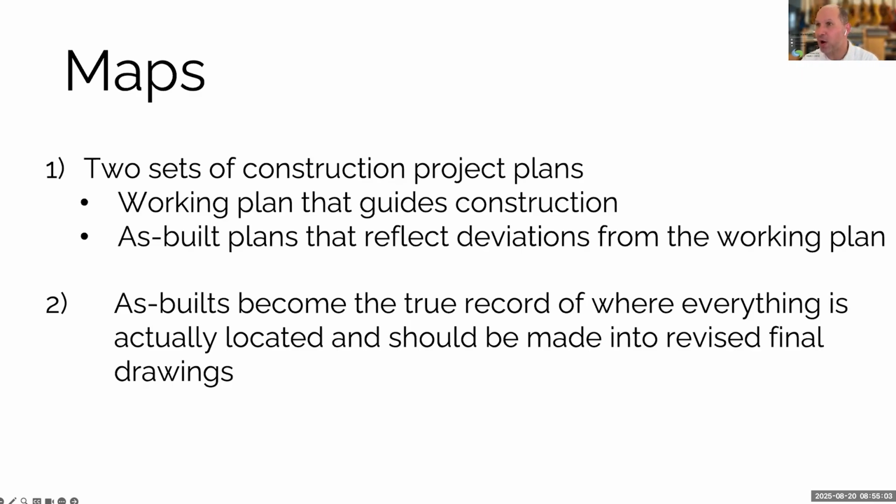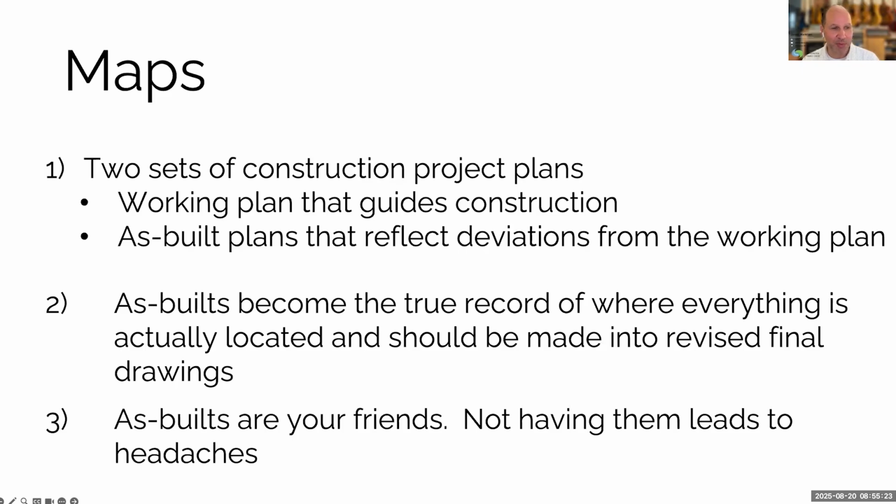It should say final drawings or something like that on there, but recognize, repairs are going to get made, things are going to get changed. And it's a good idea to work with management to make sure that those maps get updated one way or another. Sometimes that's just hand drawings on the as-builts. Other times it might actually be full-on CAD drawings and stuff. Point here is that maps are your friend.